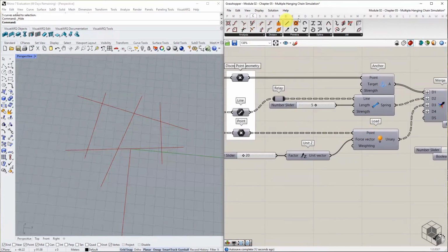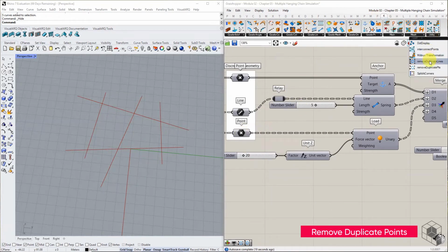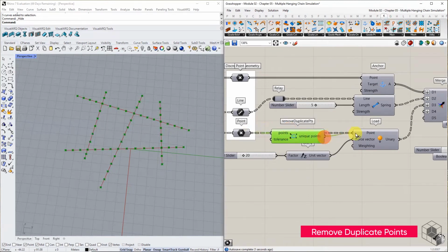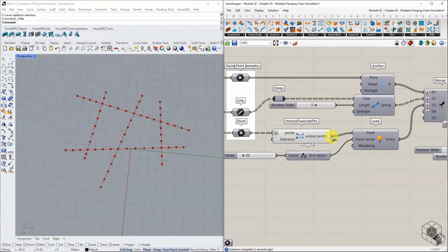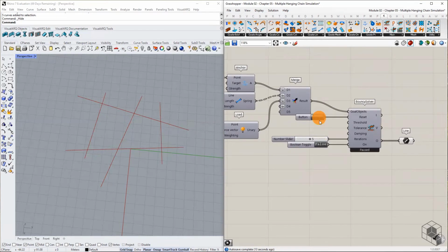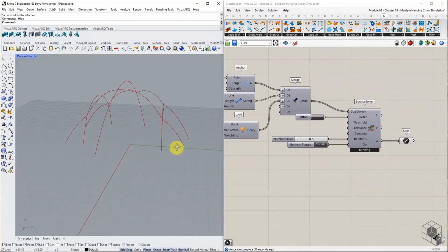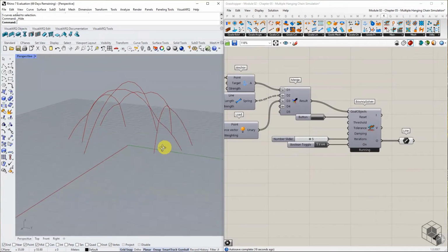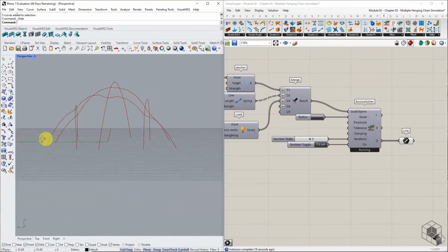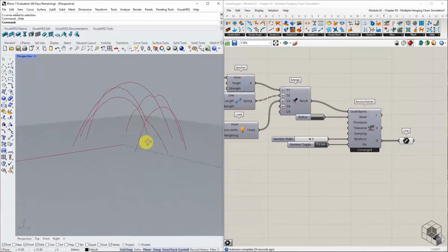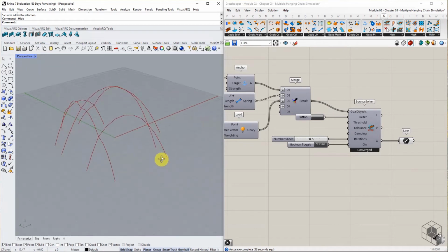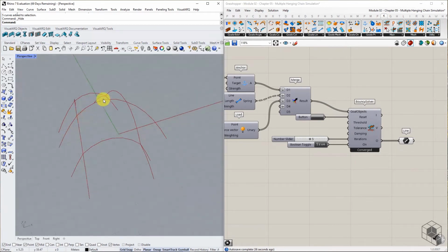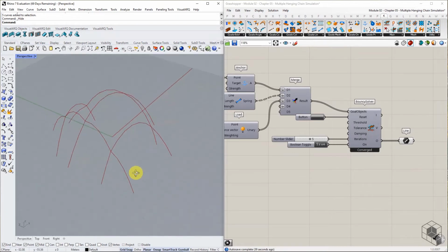Before using the points for load force, ensure there is no duplication of points in the list using the Kangaroo remove duplicate points command. Flatten the points input. Reset, and enable the solver. The resulting curve is affected by the goals of connected nodes, and networks as well. Line segments' displacement is proportional to their distance from anchor points.